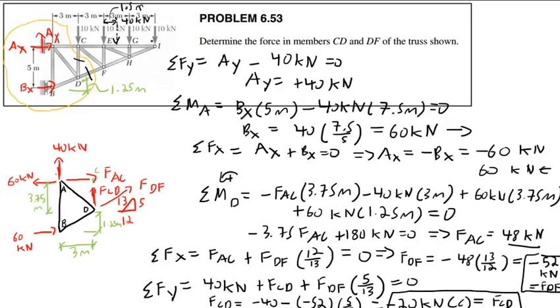I'm going to have to draw 6 to 8 free body diagrams to solve for those two stinking forces using the method of joints. But if I use the method of sections, I can draw a single diagram and leap directly to the solution for those forces. Okay, questions on this nonsense?